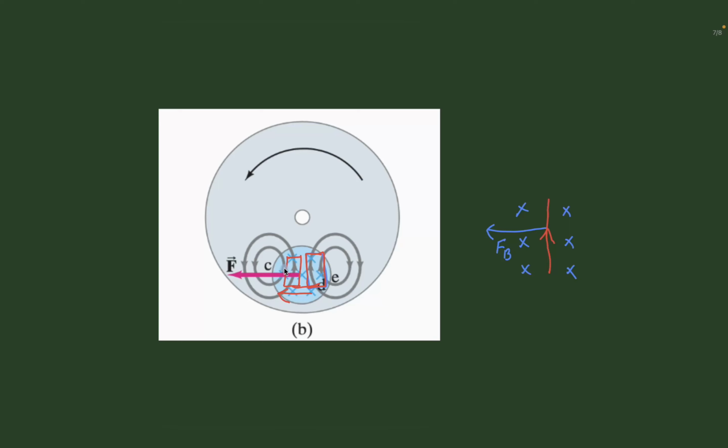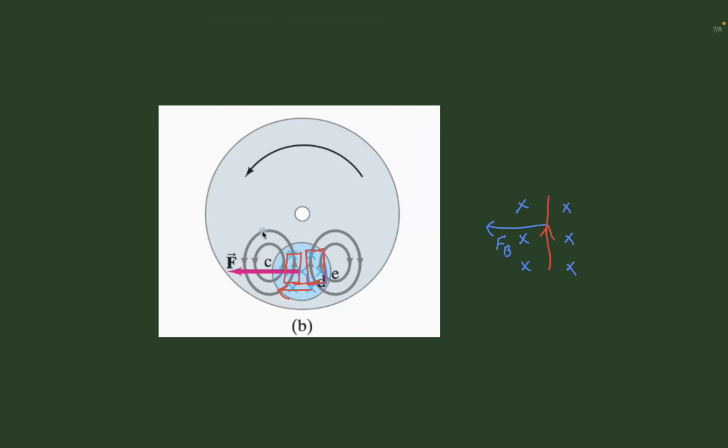Only in that region are the eddy currents going to be generated, and the eddy currents are not confined to some specific loop, because there is no loop here, but the current by itself will form a closed loop in the plane surface area of the disk or the sheet that is moving in the magnetic field. That means these eddy currents take place in the surface area of the sheets.